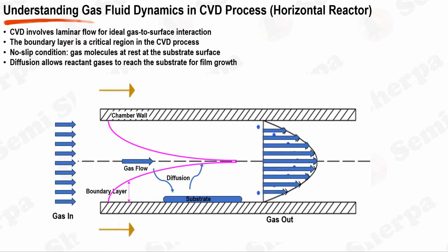The Poiseuille flow concept illuminates these dynamics, focusing on the flow of viscous fluid within a long, cylindrical pipe. This flow type is distinguished by a parabolic velocity profile, where the peak velocity occurs at the pipe's center, and velocity drops to zero at the pipe walls owing to the no-slip condition. The primary driving force for Poiseuille flow is a pressure gradient along the pipe, fostering a steady, laminar fluid flow. The concept of laminar flow is integral to this process.